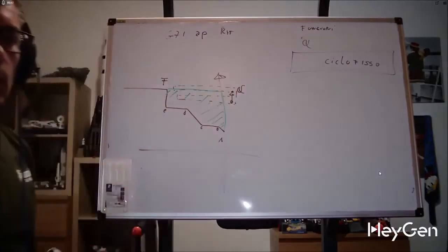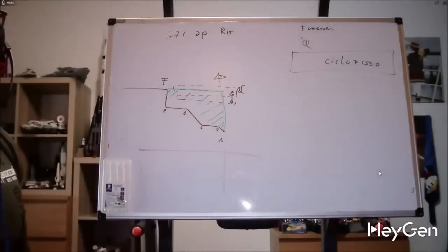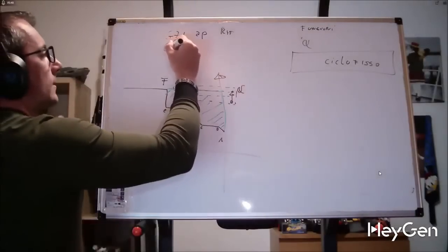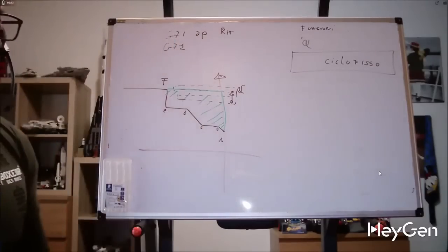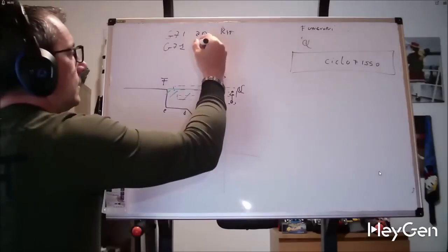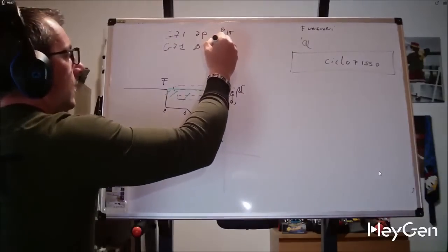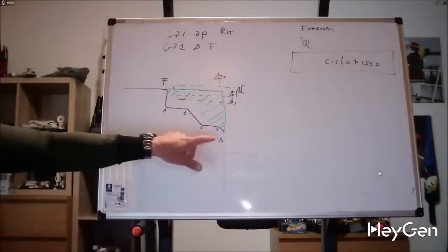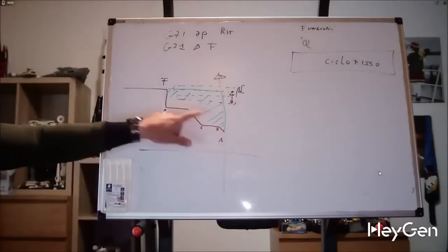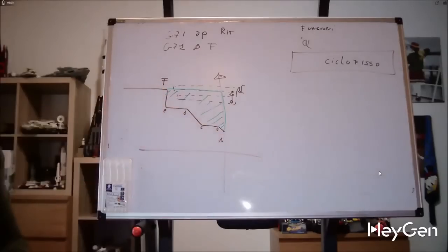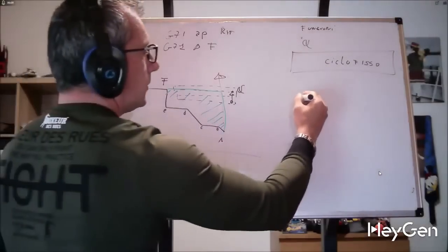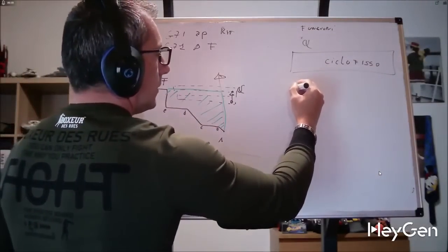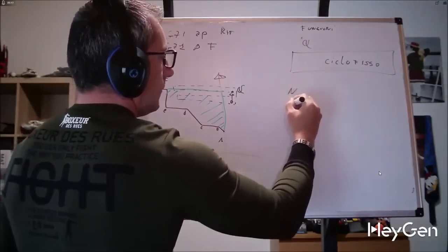Every time I come back, Fanuc provides a roughing macro in 2 lines. So below we'll find another G71, and this G71 will specify A and F, meaning where I start the profile and where I finish it, but not based on coordinates, rather on a description of the cycle that we'll find below our cycle with a series of coordinates.